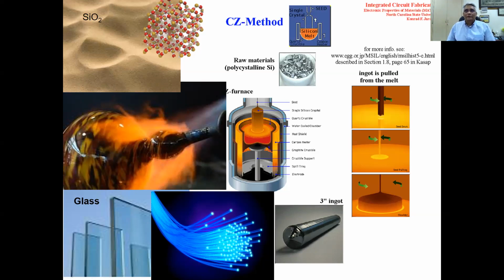And I also mentioned that to form a polycrystalline material, per se, we do not need a melt. So polycrystalline material can be obtained from powders of the raw materials. If you just heat the mixture of these powders, as a thumb rule, to about 90 to 92% of the melting point of the constituent elements, that's enough. You don't have to actually start from melts to get a polycrystalline material. But single crystals have to be grown from melts.